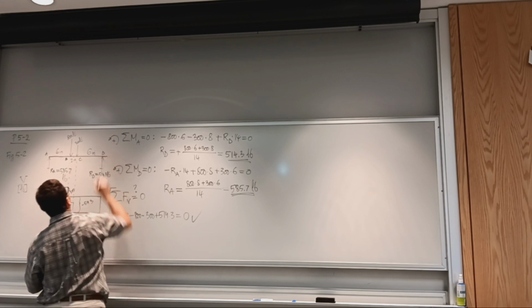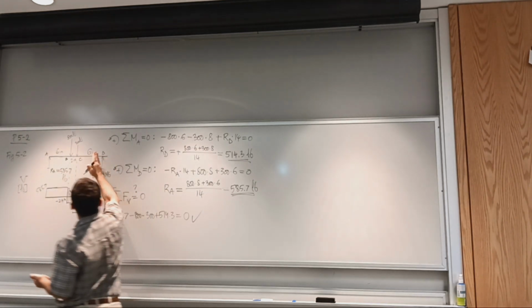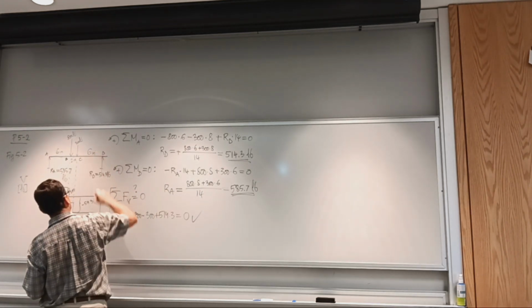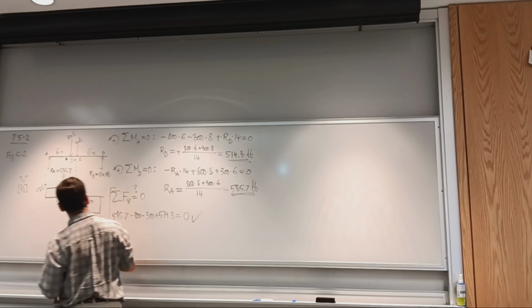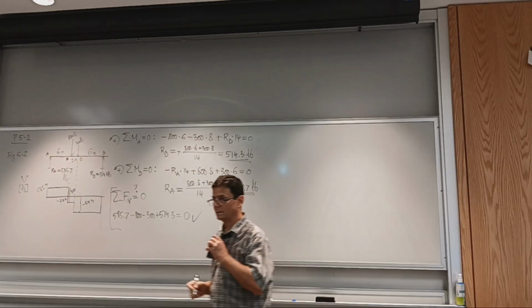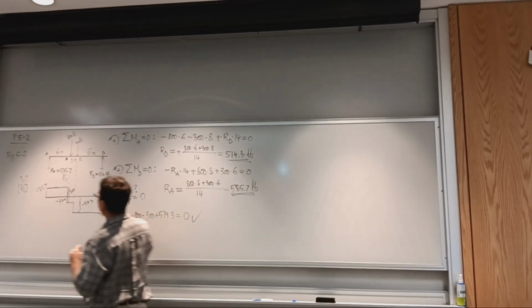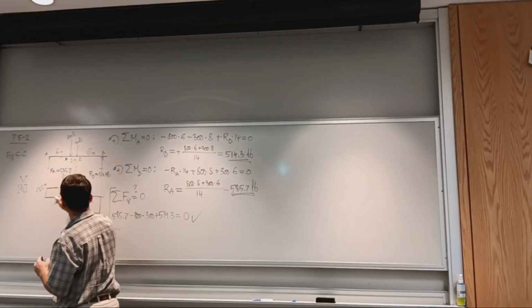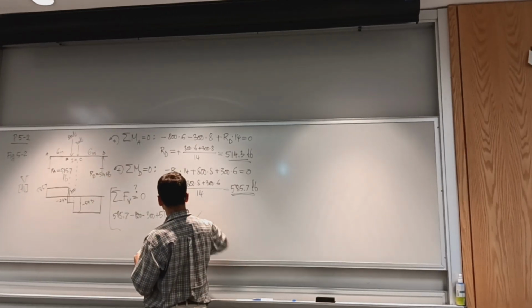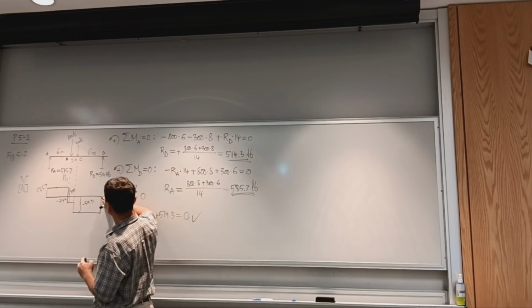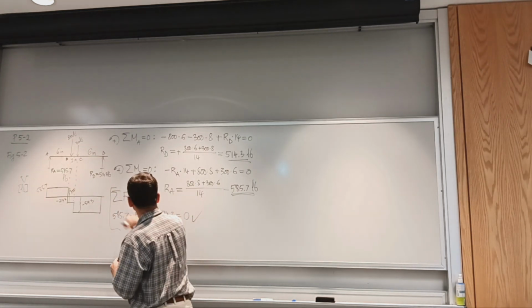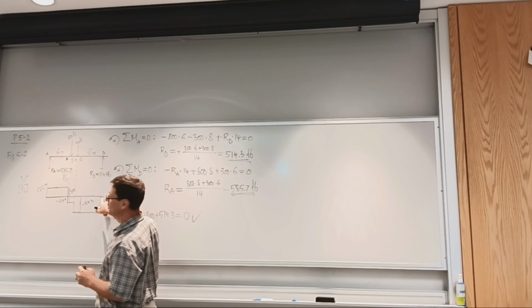And then if I have another inch of beam and I move past point D, this is going to close the shear diagram, and this is no load. Okay? And indeed, if you do it systematically, this is going to be confirmed because the diagram closes to 0. If you've got this wrong, then the diagram will not close at the end.